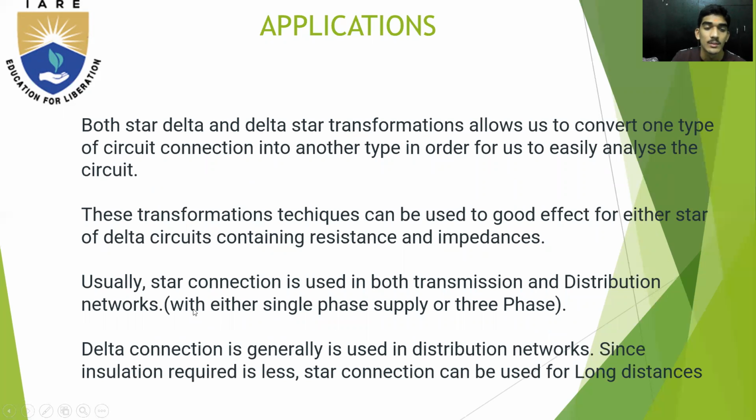Applications. Both star-delta and delta-star transformations allow us to convert one type of circuit connection into another type in order for us to easily analyze the circuit. These transformation techniques can be used to good effect for either star or delta circuits containing resistances and impedances.